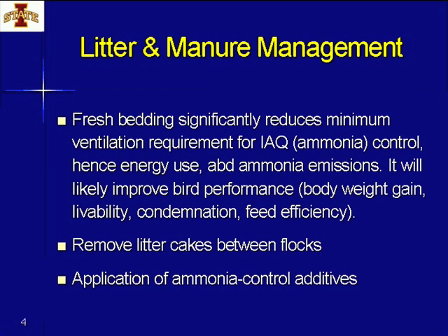So to start with, I'm going to talk about litter and manure management. We have demonstrated repeatedly that fresh bedding would significantly reduce the minimum ventilation requirement for indoor air quality, particularly for ammonia control in the case of poultry. That will lead to reduced energy use and ammonia emission.